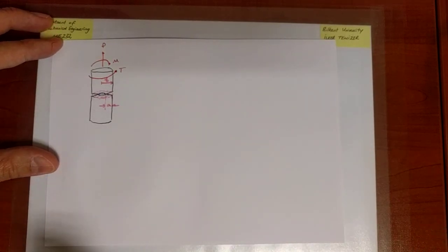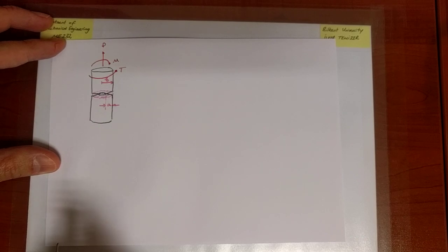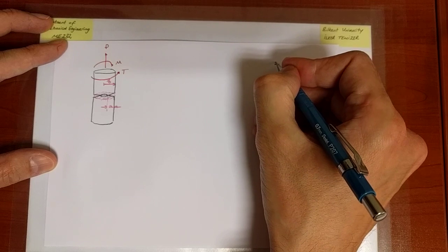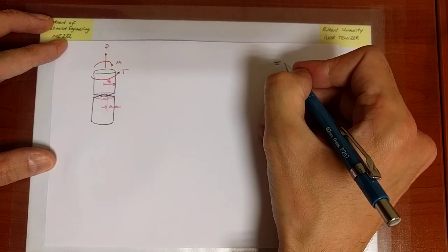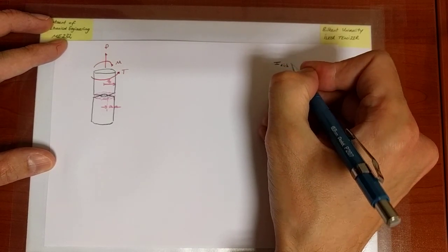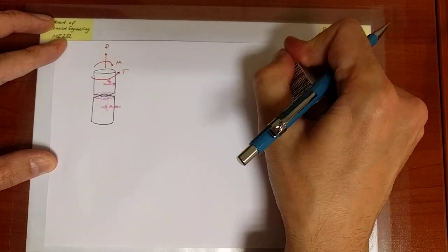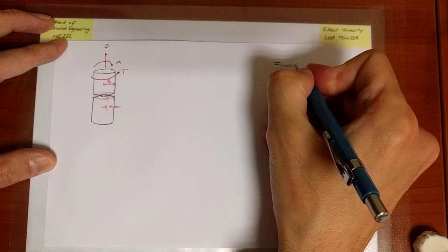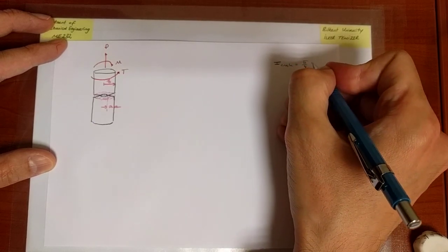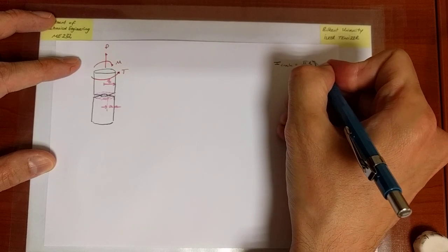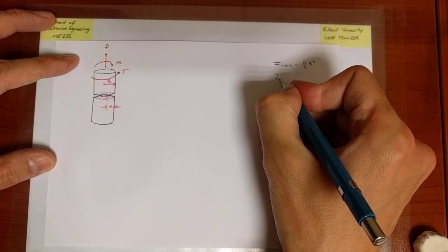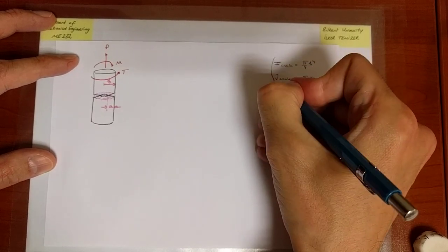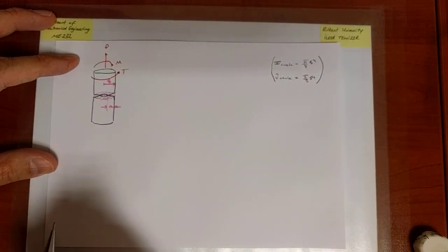And now, let us think about the different types of modes that we can have. And in doing so, let me remind you that the moment of inertia of a disk or a circle, let's say, is equal to pi over 4 r to the power 4th, which is b to the 4th in this case, and J for the circle is just twice that, it's pi over 2 b to the 4th. So we can keep those in mind because we will need them.